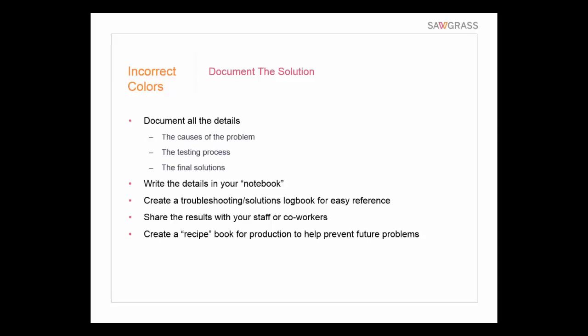When you close the heat press and you start heating, you're transferring heat from the platen to the shirt, so therefore it starts to drop, and then of course the heating elements kick in to bring it back up. And then when we open it up, it's usually at a lower temperature than when we started. If you're in a real cold environment, it may have a long time to heat back up. So these are just things that can be happening through the day to keep in mind.